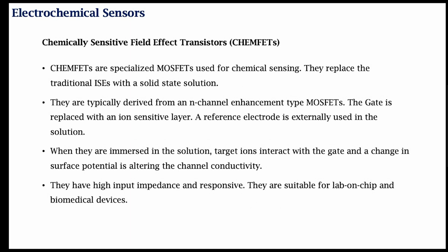So charged species at the membrane of the surface, which is acting as the gate, or the gate channel, will generate an electric field and will change the threshold of the gating mechanism, such that the drain current relates to the concentration, the transfer function.